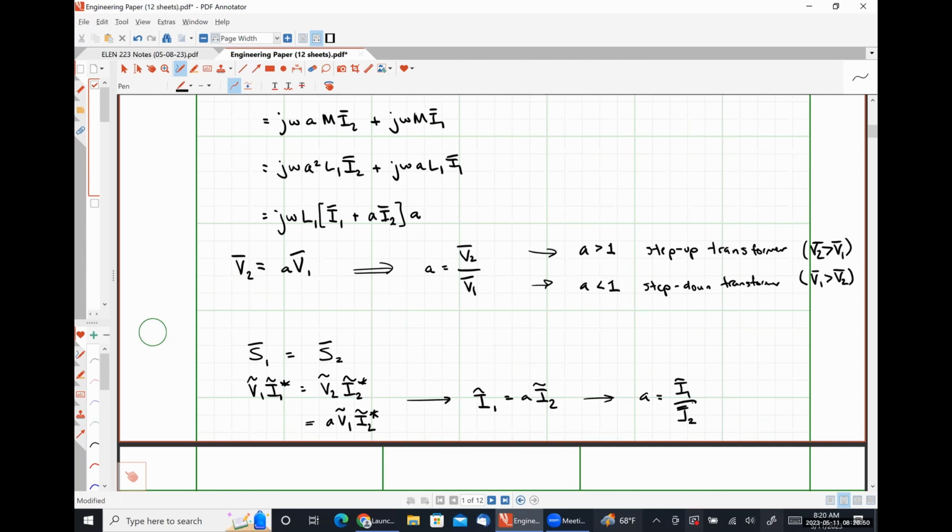Okay, so we have some understanding of the fundamental relationships here. Now let's talk a little bit about input impedance, like we talked about the other day. When we had a practical transformer, our input impedance was formed from the primary loop impedance and then some scaled version of the secondary loop impedance, right? It was omega squared, M squared divided by the secondary loop. Things are going to be even easier. It's now just going to be related to the turns ratio.